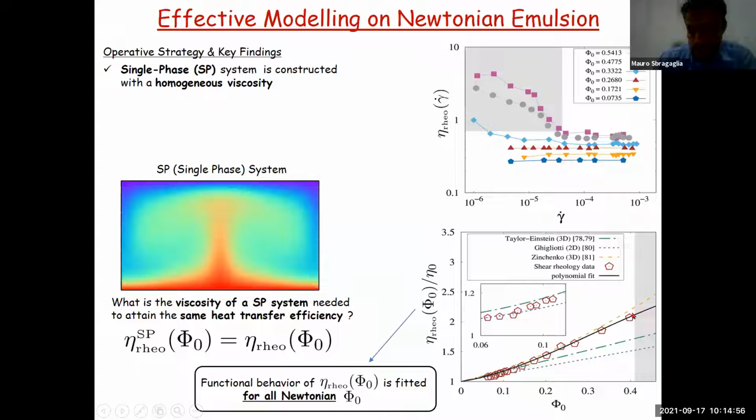We can also fit this kind of viscosity plot as a function of the emulsion concentration. So our first guess would be to take this viscosity, place it back in the single phase system, and start the numerical simulations with this global rheology to see what happens.